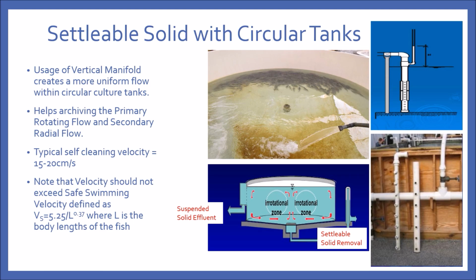To clean out the solids, the typical cleaning velocity you require is 15 to 20 cm per second. If the flow introduced is not high enough, it will not result in the formation of a vortex.